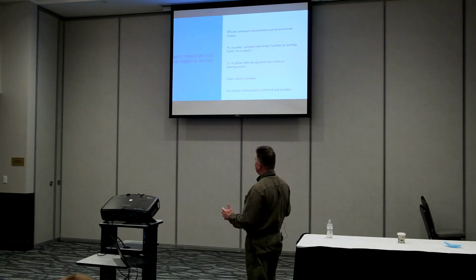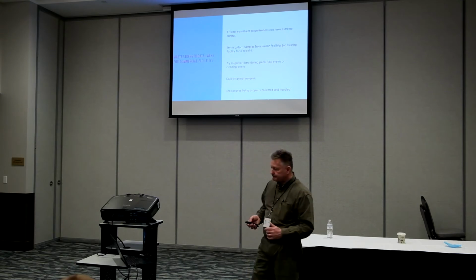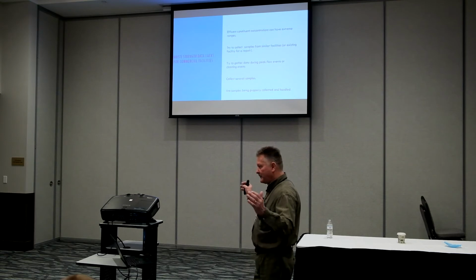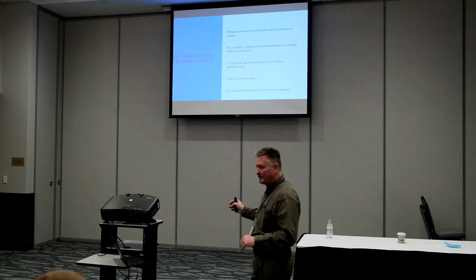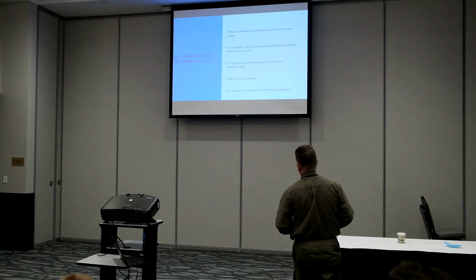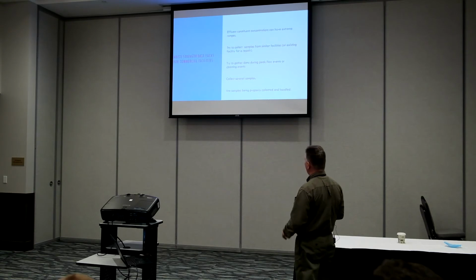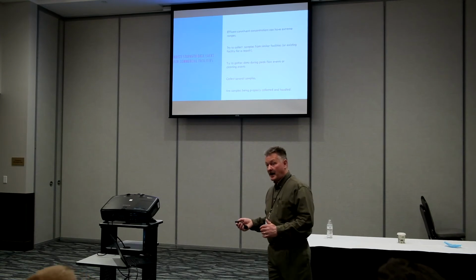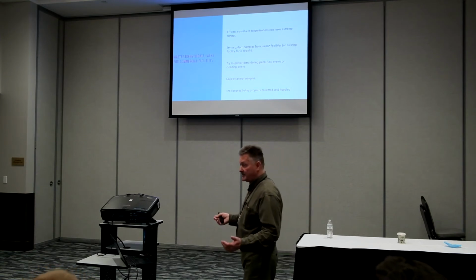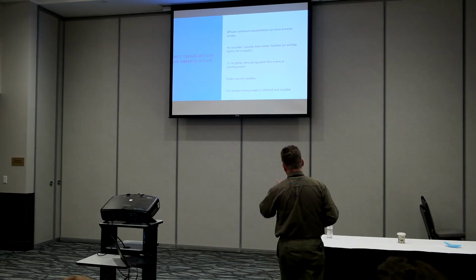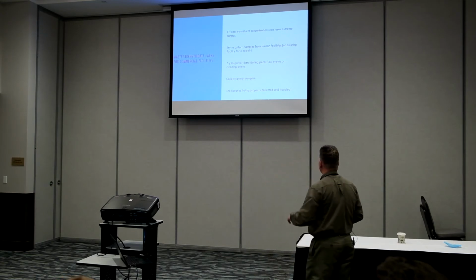Waste strength data is lacking for commercial facilities. If you were to look at it, we have a wide range. It's not like residential, where we should be about 150. Those numbers are all over the board, so we have to try to figure out what they are. Just like our flow, we want to collect from similar facilities, pay attention to the management and operation within that facility, and whether it's new or existing.